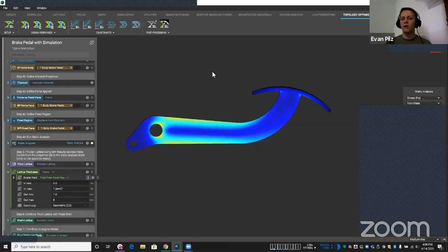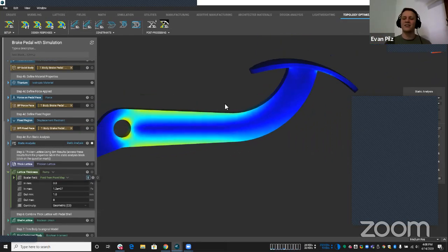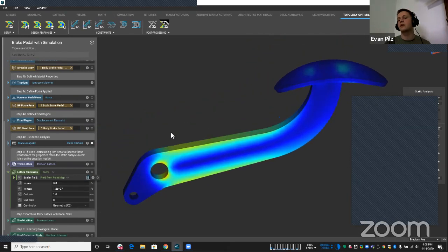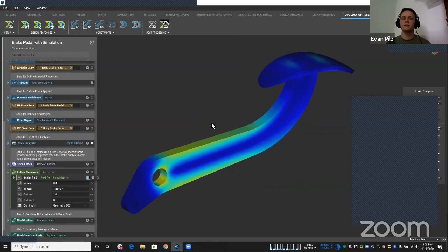It's something we're always working on, but right now you've got to think about it before you start designing, right? So if your layer height is something like 20 micron, don't give your part a feature that's a single micron thick, because you can't print that. But a lot of it's going to be possible to design around inside of nTop as well. We may not have a specific thing that says don't let this get below 2 microns thin.